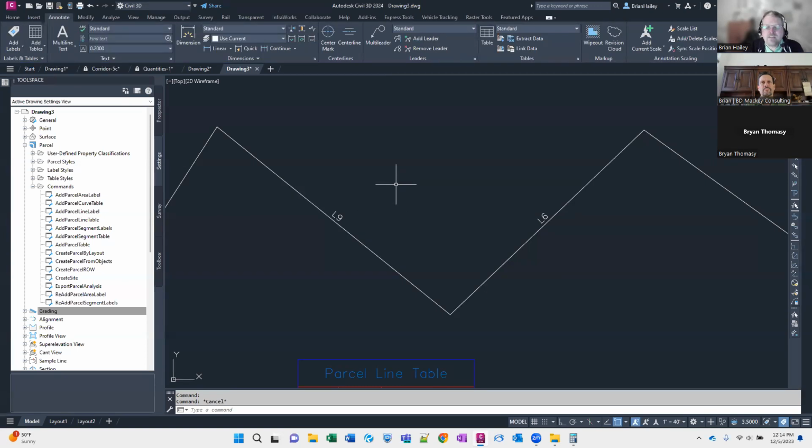Right. So if it is giving you prompts or anything, pound the escape key several million times. All right. At least twice, once to end the command and once to deselect the objects, and then just hit enter to repeat the last command. And now you get your settings. So this is where I would go check to see if maybe something odd is going on in here.